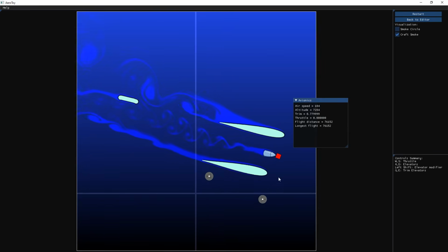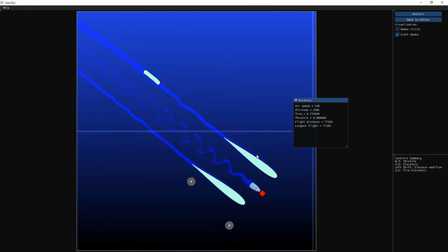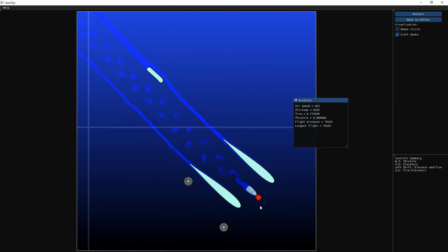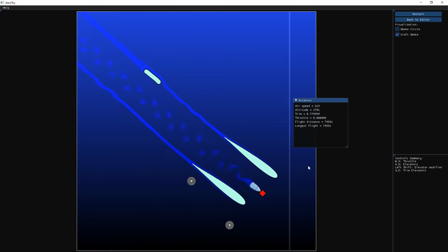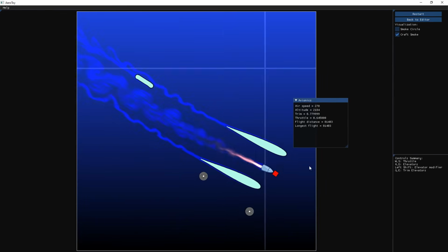But we've got that centre of mass nicely far forward at the front of the aircraft, so we're naturally pitching down into a dive. Airspeed is picking back up and we've got control again. So let's put the engine back on again and we'll see if we can get a nice landing here.